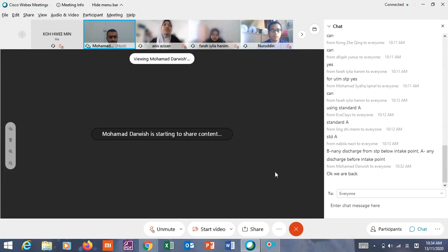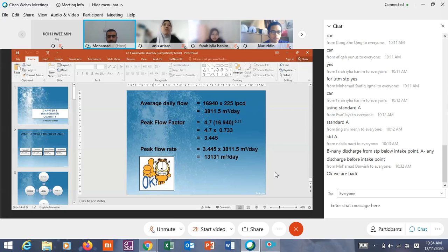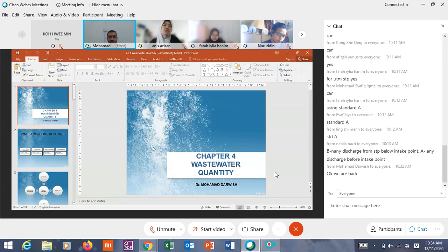Okay. Now, in the previous chapters, our discussion was only about the characteristics of wastewater. Now, if we want to go for the design of a wastewater treatment plant, that means we have to know the characteristics of wastewater and also the quantity of wastewater: how much volume, how much flow of wastewater is coming or is to be generated. And the production of wastewater depends mainly on what? It depends mainly on the water demand.